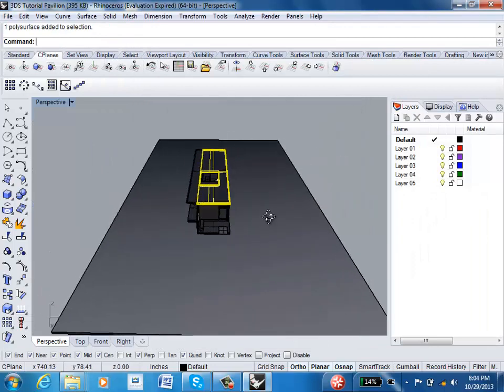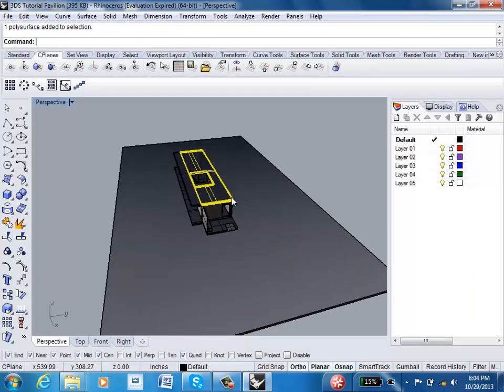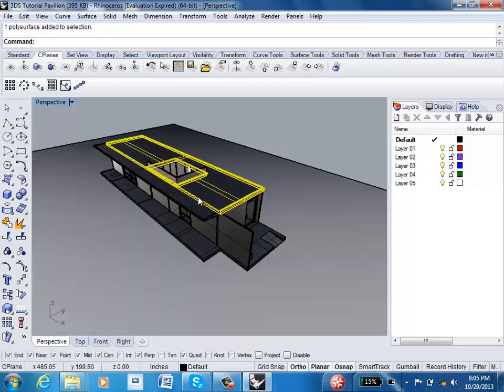So if I select an object, I can type in the command mesh, and that will bring up a series of options that will allow me to convert this solid geometry into a mesh. You only really need to do that, like I said, if you have complex geometries. Everything in here is relatively simple geometry, so we're going to let the export process do that for us.